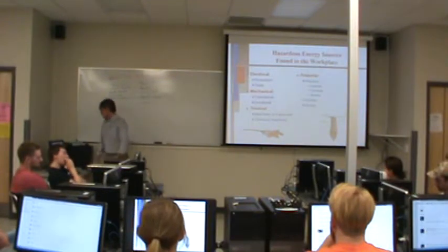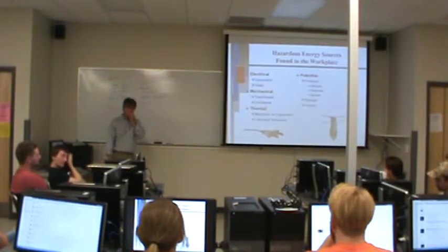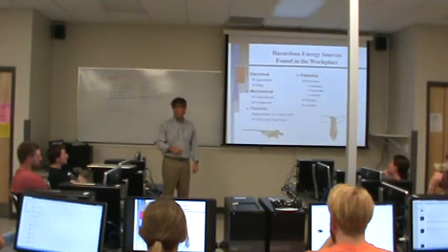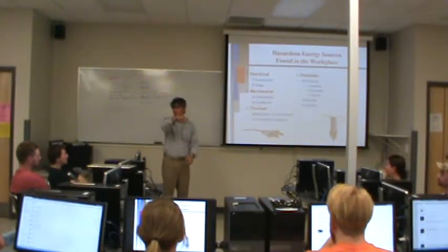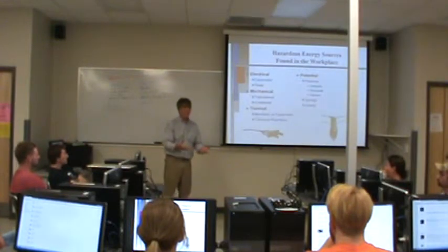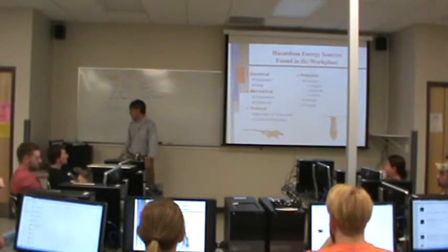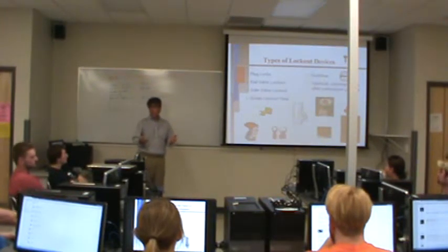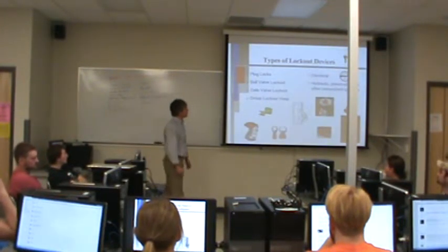Another thing you have to think about, if you have an overhead crane and the crane is shut down for emergency, do you want it to just drop the load? Probably not, right? You want it to hold the load. If it drops the load, it could drop it onto someone. So you have to think about those things when you design a system and decide how it fails safe. How do you want to fail safe?